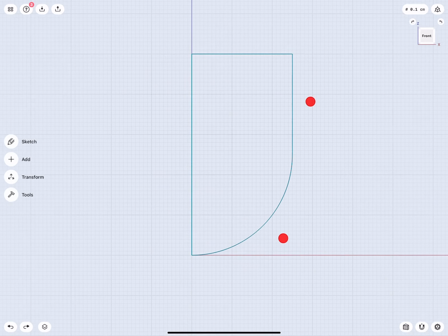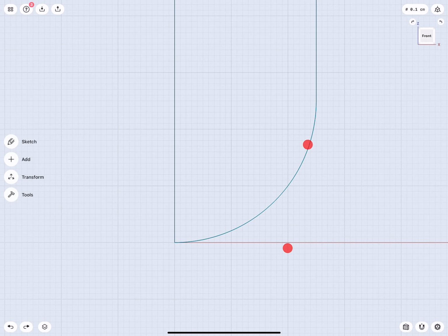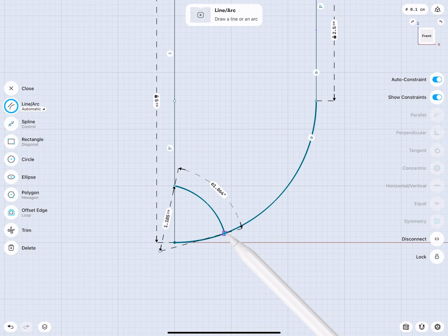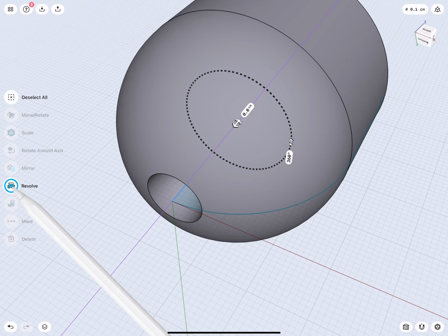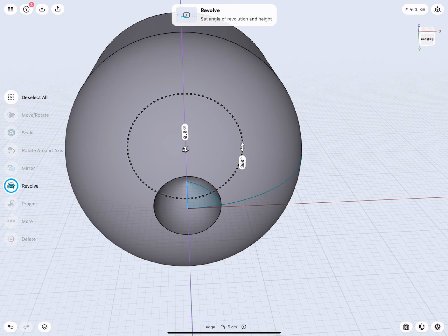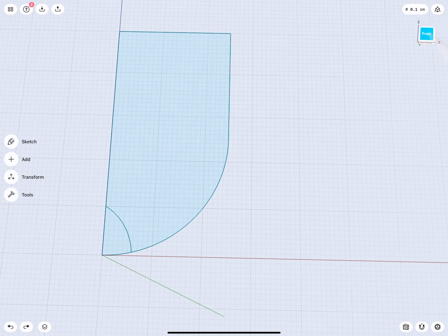The bottom part has actually a small cavity in the shape of a domed surface too. So somewhere here, we need to put in a dome too. Now, how can we make sure that the shape, for example, is nice and round? So I do something like this here on purpose, so you can see the problem we see. There, this is not a circular shape. This is more like a cone shape. So let me show you how we adjust the sketch now.